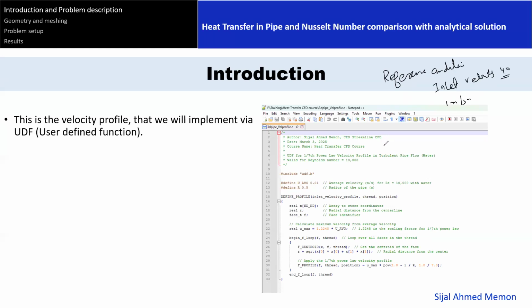Similarly, like we are now going to solve this case, we are talking about the bulk temperature. Why the bulk or mean temperature? Because that does not change locally. What if the flow was external flow? In external flow, our bulk temperature calculation would have been very simple, because I would provide my inlet temperature condition to the problem.